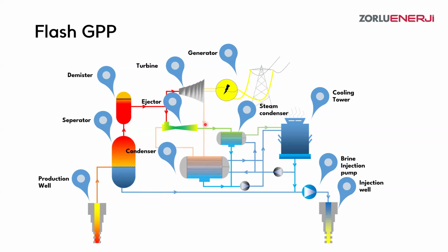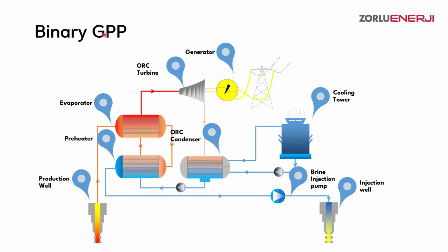And also for the steam phase, it is an option to take into consideration because you could have a great amount of steam, and due to that fact, you could have a great amount of energy in here. Maybe you cannot use that steam energy in the steam turbine, but you can transfer that heat to a binary fluid and use it in this ORC cycle, okay?